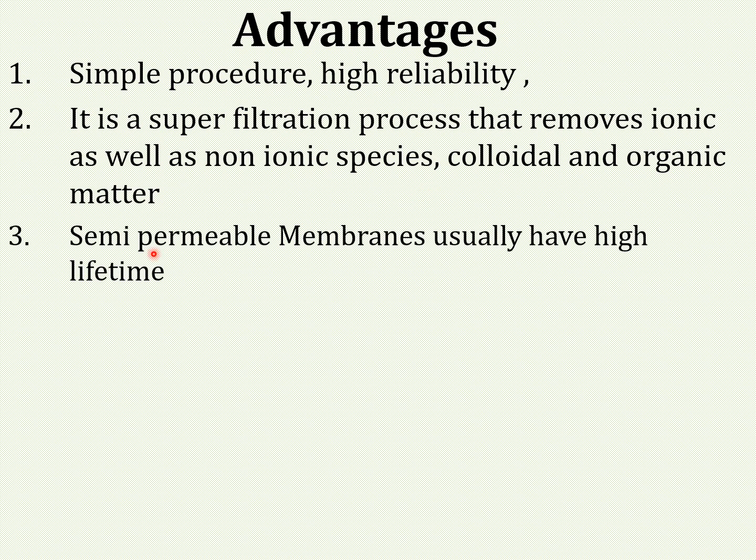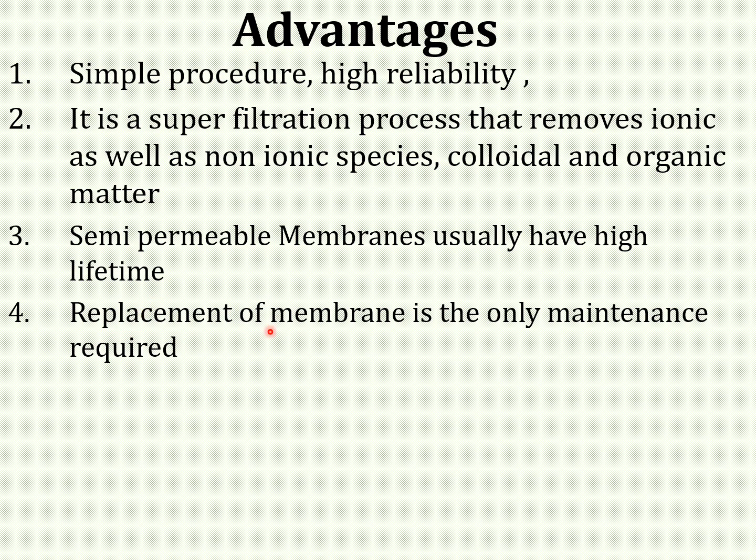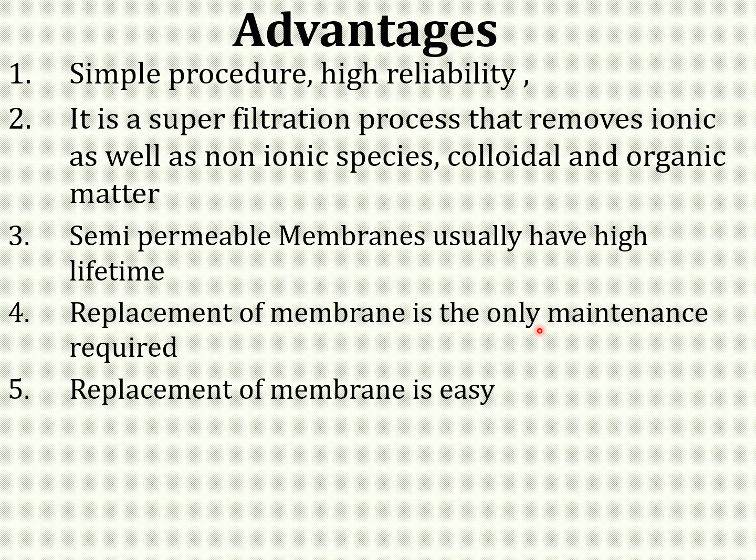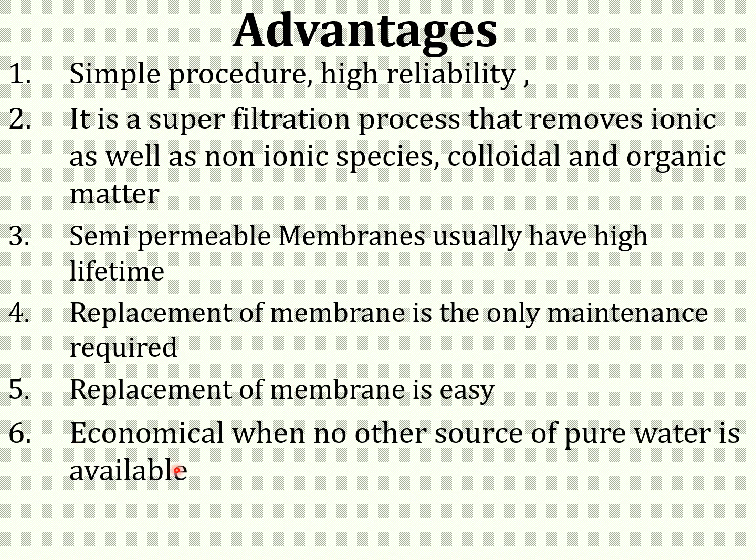Well, coming to the semi-permeable membrane, usually it has a very high lifetime, and the replacement of the membrane is done in 2 years or so. The replacement is the only maintenance that is required in this process, and the replacement of the membrane is very easy. Also, reverse osmosis is considered economical when no other source of pure water is available.